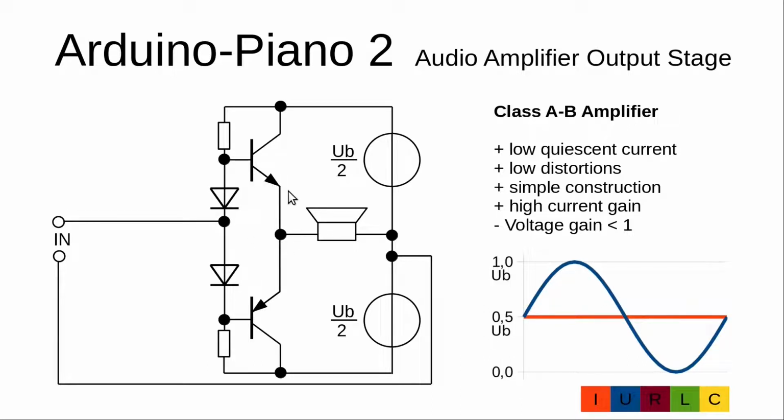The temperature effect on the base-emitter diode could result in a big cross current through these two transistors. To limit the cross current, additional resistors are necessary here and here, and that is the reason why the voltage gain even in this circuit is in reality below 1.